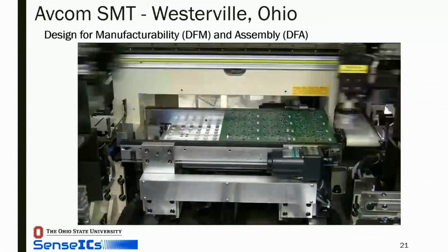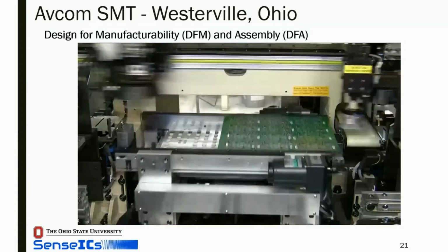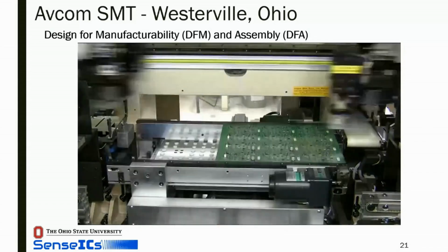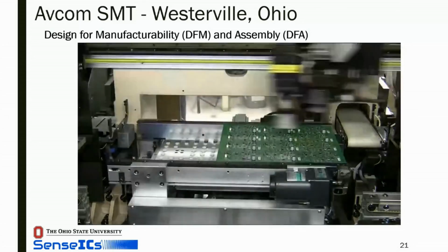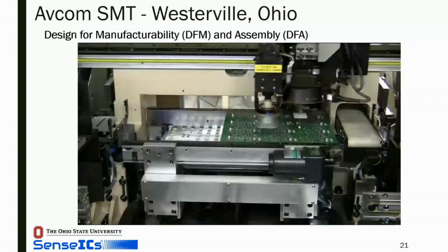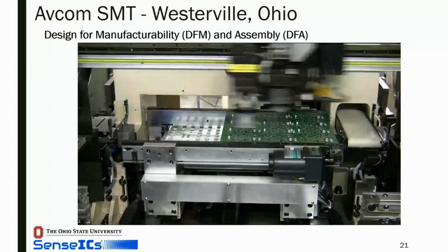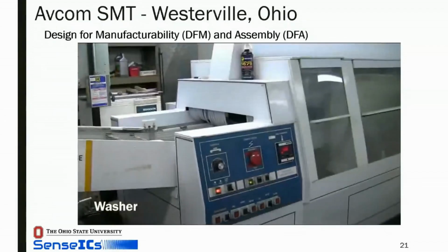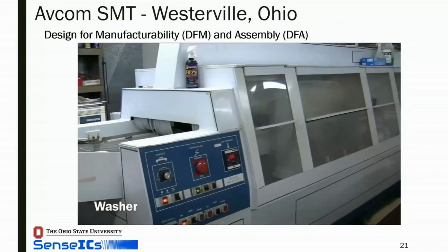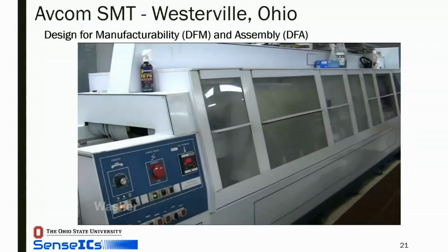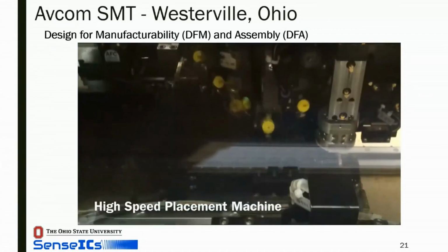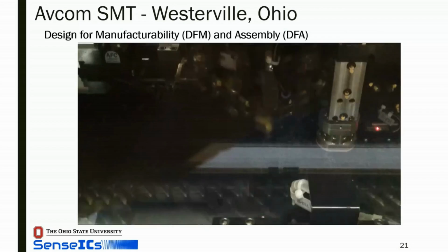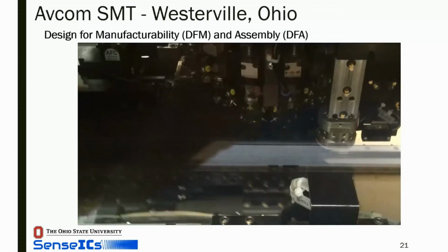During this process, when it first places the components on the board, are they loose or are they stuck in at least in some partial way? Yeah, the components come in what are called reels, or tubes. The people who make the ICs and the resistors have a packaging method that is compatible with these machines. So they go into the oven to melt the solder and make a good connection, right?